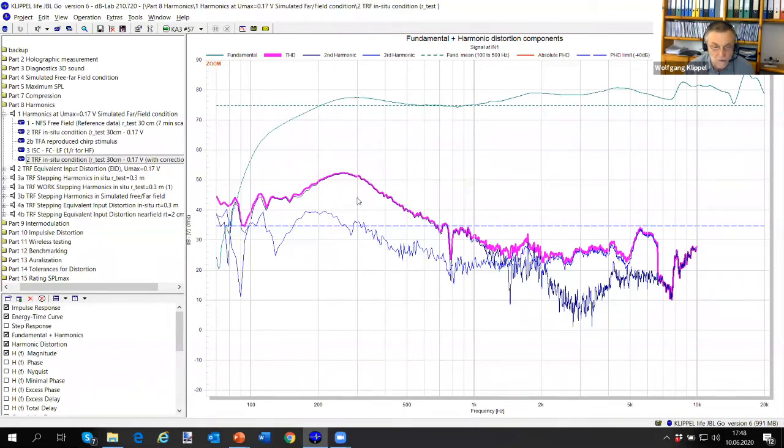Let's go here to 300 Hertz to 600 Hertz. That's about 12 dB from this point to that point. And this is just like displacement. So we have one displacement, it goes down by 12 dB per octave, times current, which in this frequency range is almost constant. That comes from BL.